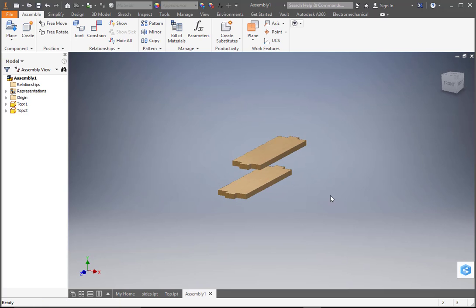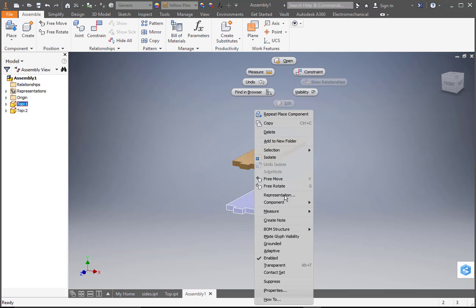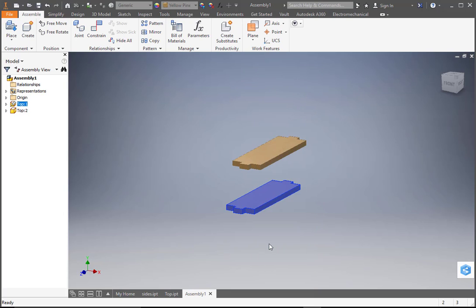I'm not too worried about that at the moment, but what I am going to do is take this object, everything's free moving from it, I'm going to take that part and lock it into place, because then everything gets locked into place with it. So if you watch this for a second, I'm going to click on that, right click, and make it grounded. So that object now, if I click and drag, can't move. And you see it's got a little drawing pin next to it to show it can't move. This one can move wherever I want it still. But I'm going to let that one hang loose for a minute whilst I get on with this one.